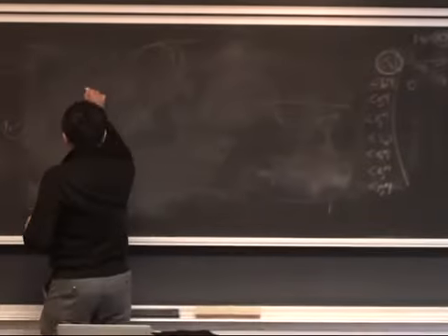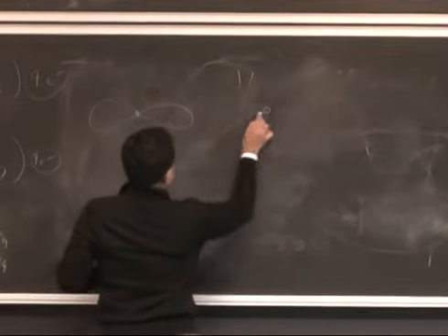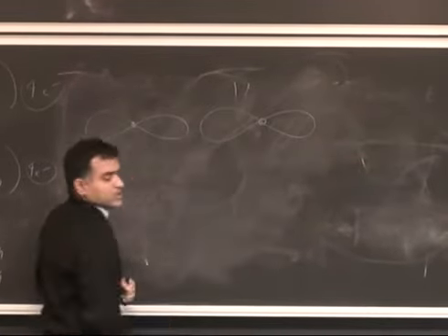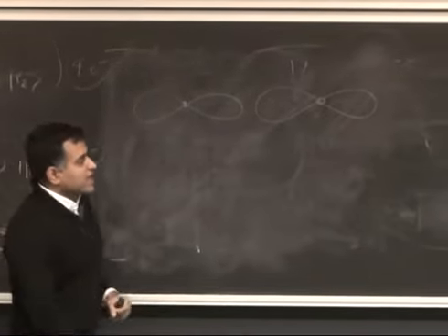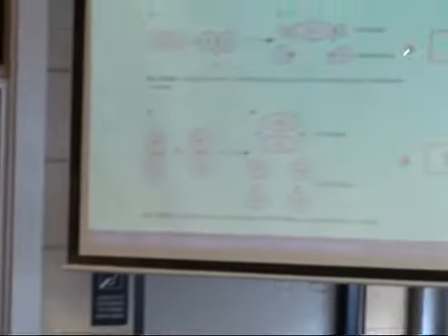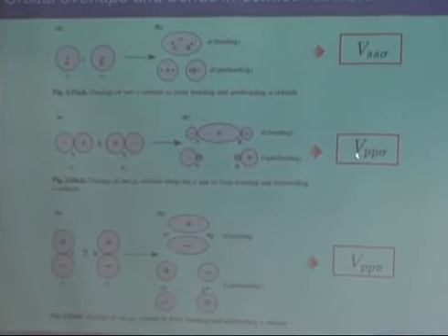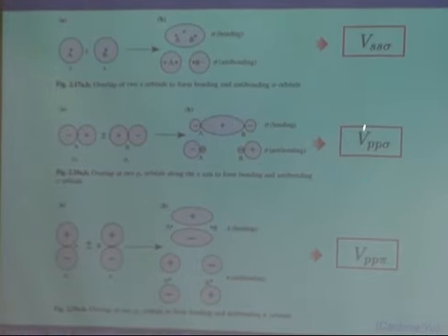So if I have gallium and arsenic, here's a px. Here's another px. That's one way to chemically bond the two. There's one possibility of chemical bonding. Right? And that bonding is called the sigma bonding when they are kind of end to end or lined up like that. Right? And then that energy again will form antibonding and bonding, and the lower energy will be the VPP sigma for us.